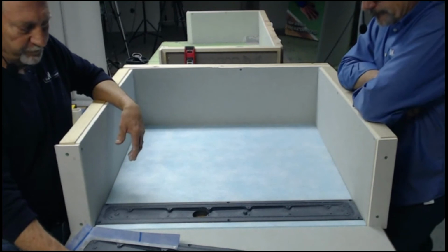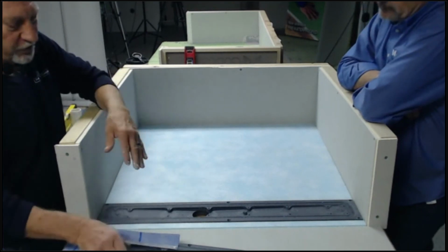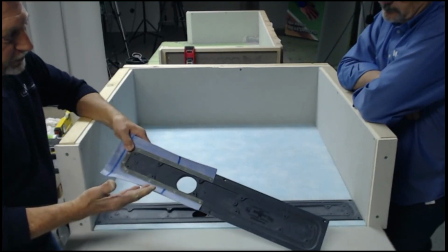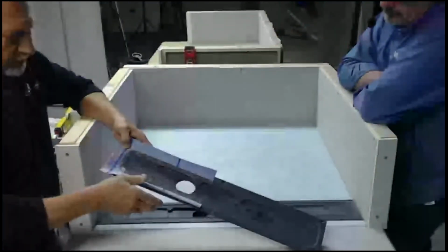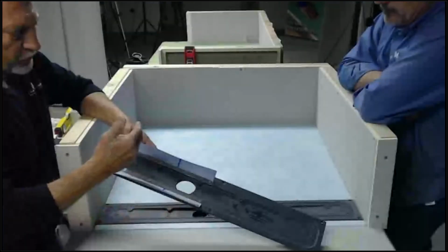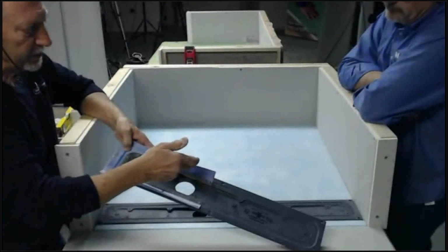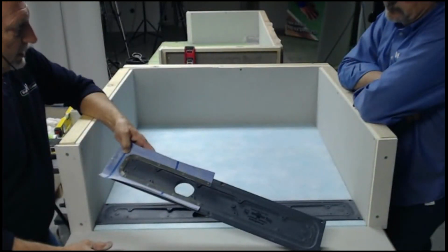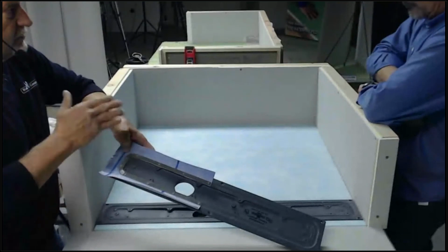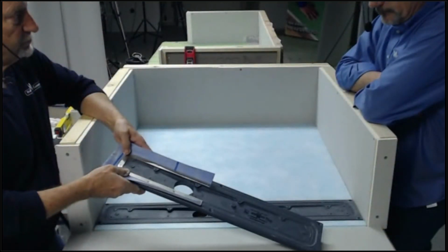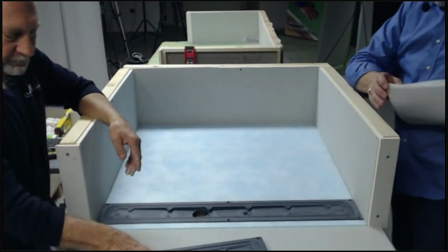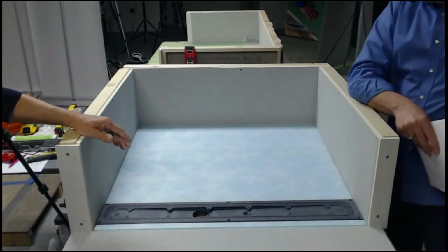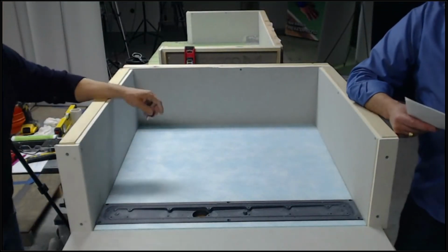Yep. So as you can see with this up here, that it has a clamping ring. And now this is just a 1/2 clamping ring, just for illustration purposes. So again, we'll chemically and mechanically seal the membrane to the drain. Yep. Again, it's a bulletproof installation. Okay. Looks good. I think that pretty much covers all that.